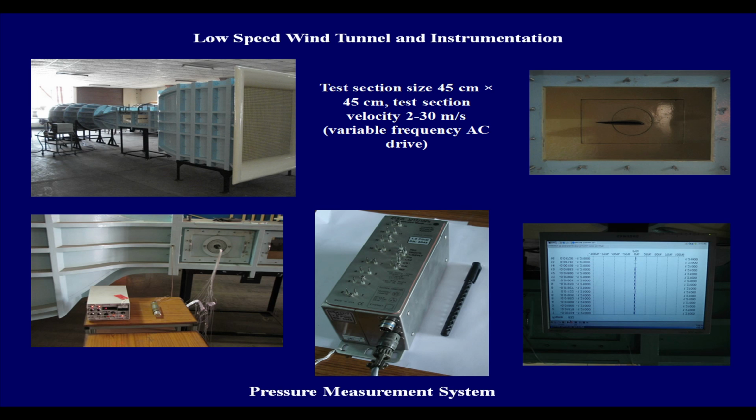results. So if you say that I have sized my finite wing in such a manner that it stretches about, say, 80% of the width of the cross section of the tunnel, then probably you are not going to do a good job in terms of the measurement. Whether it's forces or pressures, it really doesn't matter, because that gap is too small. The wall is certainly going to have an effect on the roll-up. So these are issues that you have to look at.